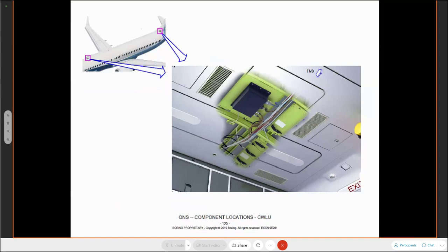Wired connections either to the flight deck, to the P61 panel, or to the network file server in the E&E bay, you still, the portable maintenance devices still have to have the correct software, the correct security certificates, to allow them access to the network file server, but you don't have to put a password in. The password is only applicable to wireless connections.